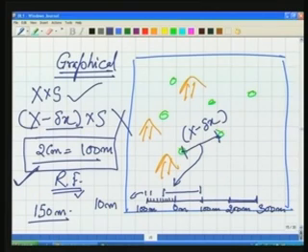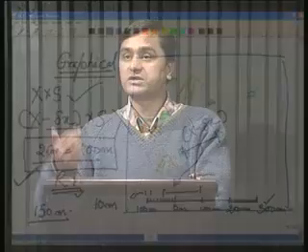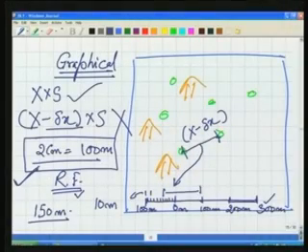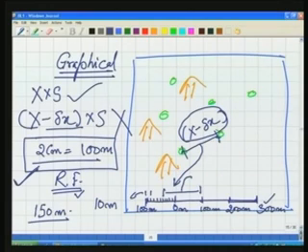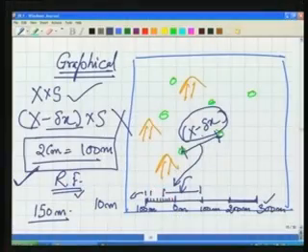Well, if you have a graphical scale on the map, what is happening there now? Whatever is the amount of the shrinkage which has occurred between these 2 points, we can assume the same shrinkage is taking place in the graphical scale also. So the graphical scale also shrinks by the same amount. Even if we are measuring x minus delta x, we will measure it here, because this scale has also shrunk by the same amount. The distance which we compute between these 2 points on the ground will be the same distance. So that is one big advantage of the graphical scale.